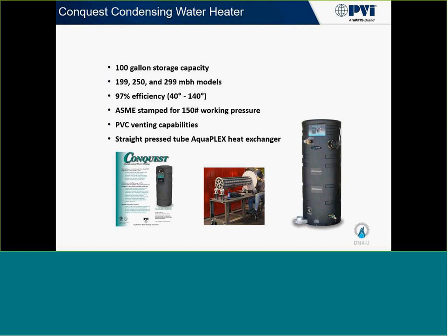So here's a picture of the smaller, the 100-gallon heat exchanger. You'll see it's a vertical fire tube design. If you notice, the fire tubes are crimped, and what that's there for is to slow down our combustion in order to scrub as much heat as possible into that water. If those were just full open tubes, the heat would travel too fast through those tubes to scrub off into that water. So that's why we slow it down with that crimping.